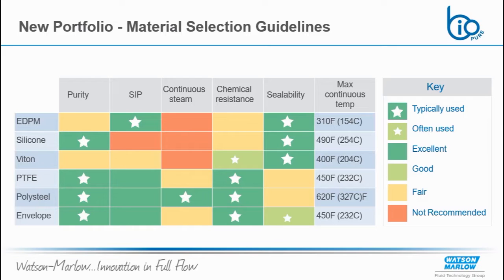However, they do not seal as easily as rubber compounds. So if ease of installation and sealability is critical to your customer, then a PTFE gasket might not be the ultimate choice. That being said, there are customers that successfully use PTFE gaskets, and in those applications, it might be that chemical resistance and purity are most critical to them.